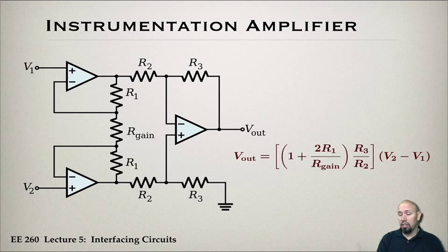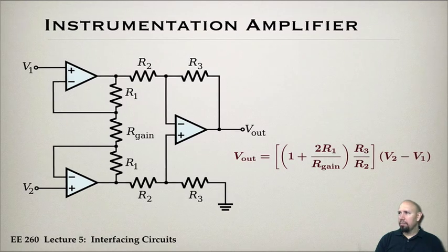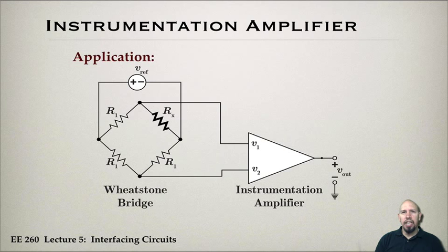Generally, we're going to want amplification. So that's why we have this configuration. Now, it's very standard for all of this to be packaged into a single chip. And what's allowed then is R gain to be selected outside the chip. In other words, by putting an appropriate resistor in, I can vary this gain overall. So that's very common. So where would we use an instrumentation amplifier?